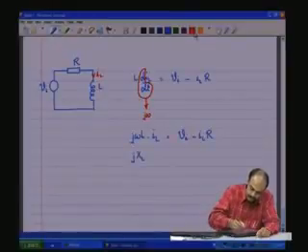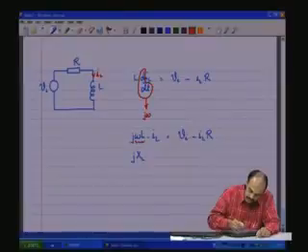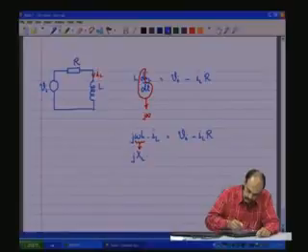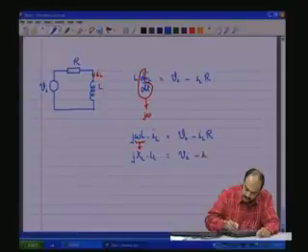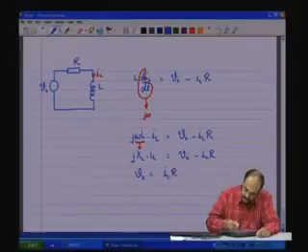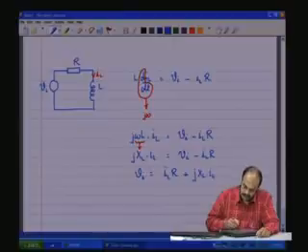You see that omega L is the inductive reactance into IL, which is equal to Vi minus IL into R. So, take IL into R onto this side, you see that Vi equals IL into R plus jXL into IL.